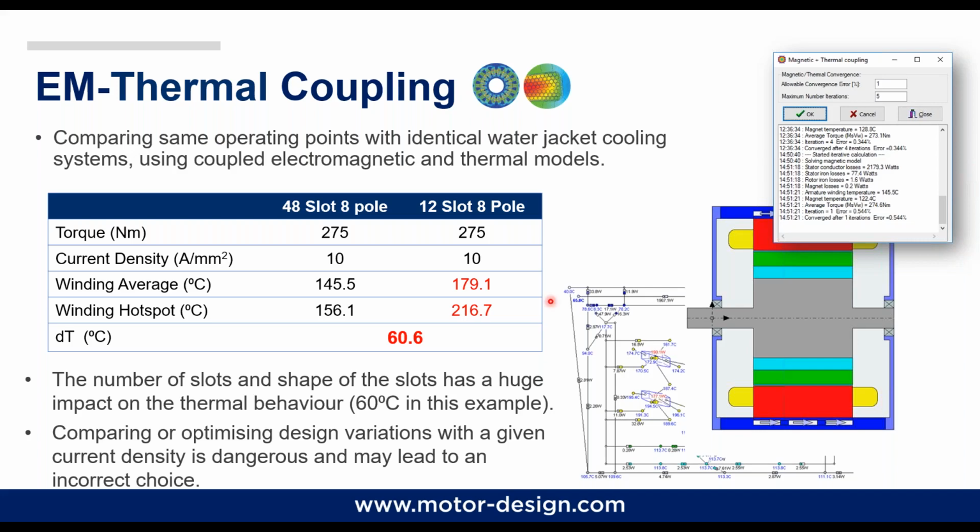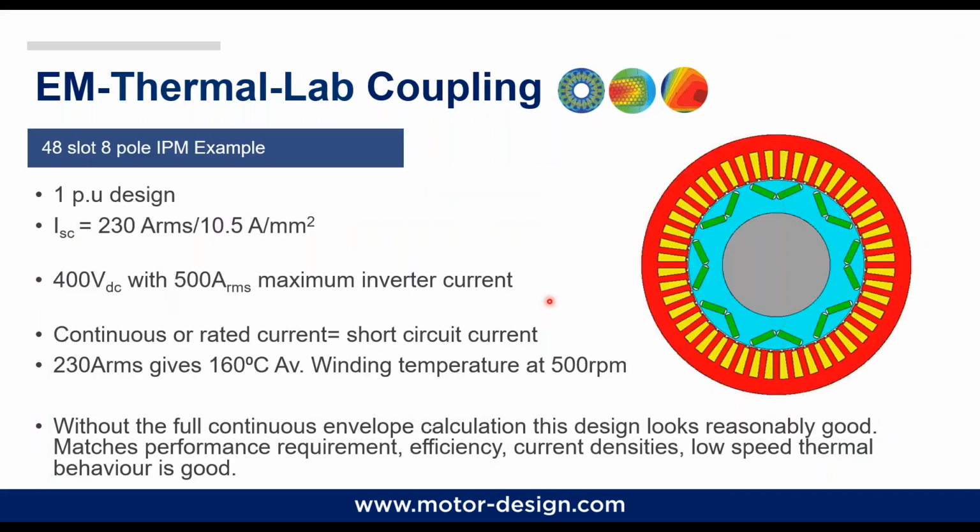I didn't include any drive cycle analysis in here, but thanks to the control model that we've got, we can study and analyze the electromagnetic behavior of the machine during, for example, a duty cycle. Let's imagine an electric car. We can study a typical drive cycle, which is already inside MotorCAD, for example a US06 or WLTP or whatever. First of all, we study the electromagnetic behavior of our electric motor during that drive cycle.